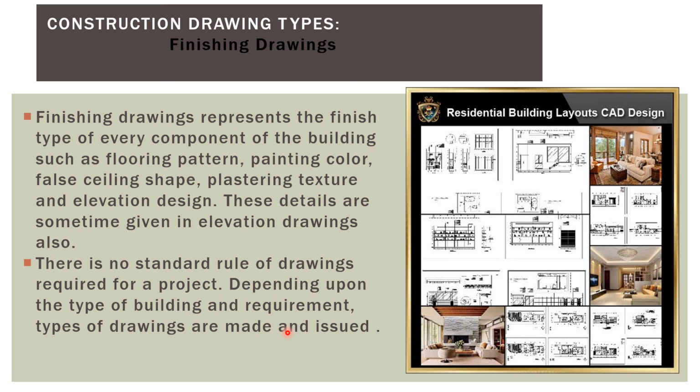There is no hard and fast rule for making these drawings, and you can put the section up and beam details at the bottom, so you can arrange things up and down. But the main thing is that you should provide details of all elements on the drawing, so that the person who is going to construct does not face any issues.